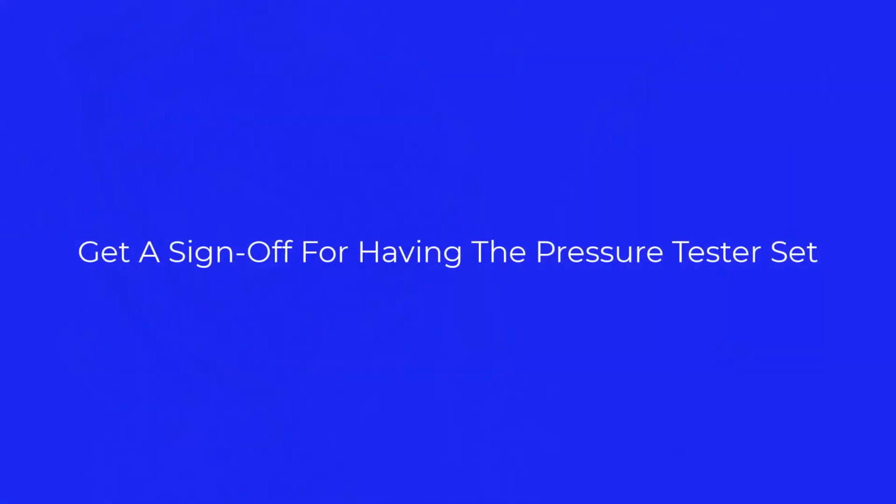Once you've done this, you're going to go to lab staff. You're going to have them sign off, show them that you have the pressure tester installed, that it's set to 20 psi, and let them know you don't have any leaks unless you do. And if you find leaks, go ahead and point those out, and then we'll sign off on your paperwork.